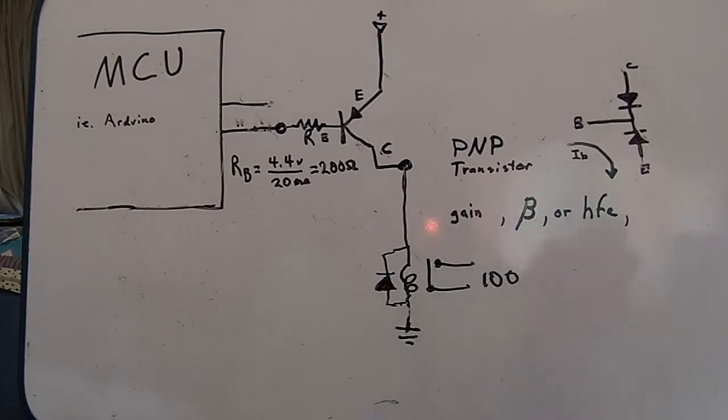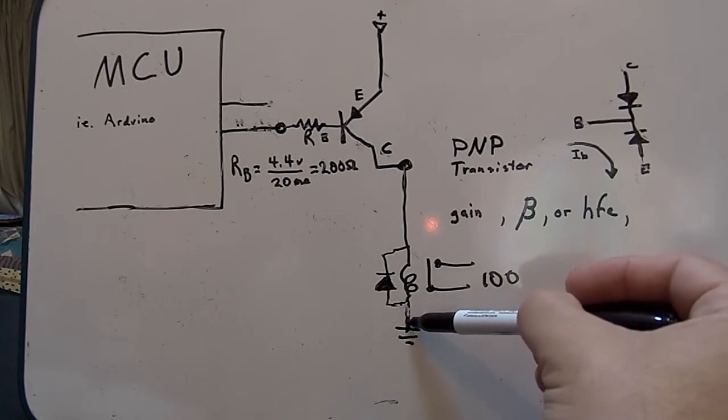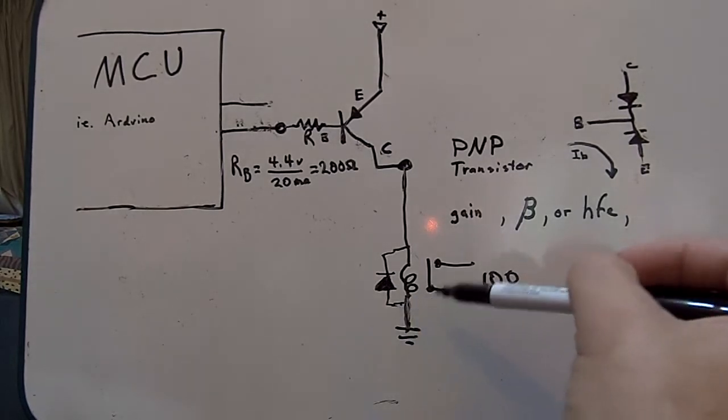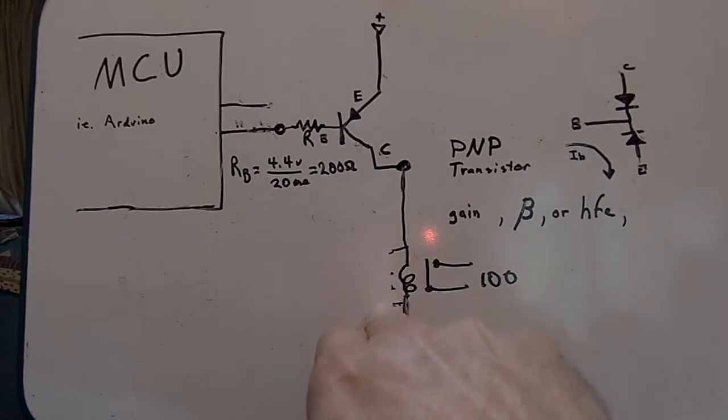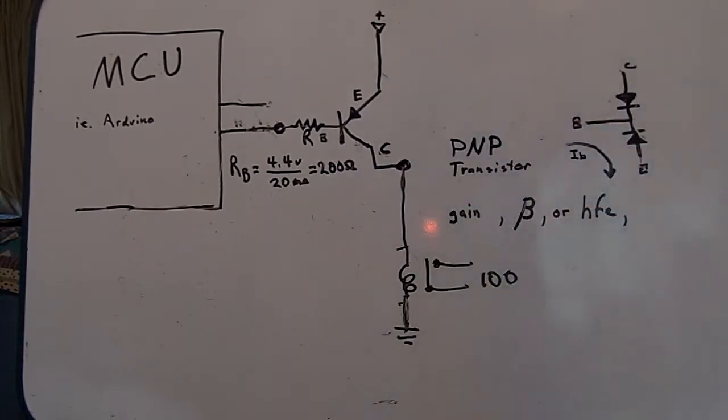Kind of kill some of that energy, even if it's backwards energy from the collapsing field. So some say you need to derate your contacts slightly when you use a snubber diode, because you're getting a less robust slam on the contacts. Which again is the reason why I might just eliminate the thing and use a transistor with plenty of peak inverse voltage, you know, to withstand at least 7 times what the relay would be seeing. So if it was a 5-volt relay, maybe I'd be comfortable seeing a transistor with at least 35 volts peak inverse ratings on it. But I'm getting into the nitty-gritty there. Normally you'll see that diode there.